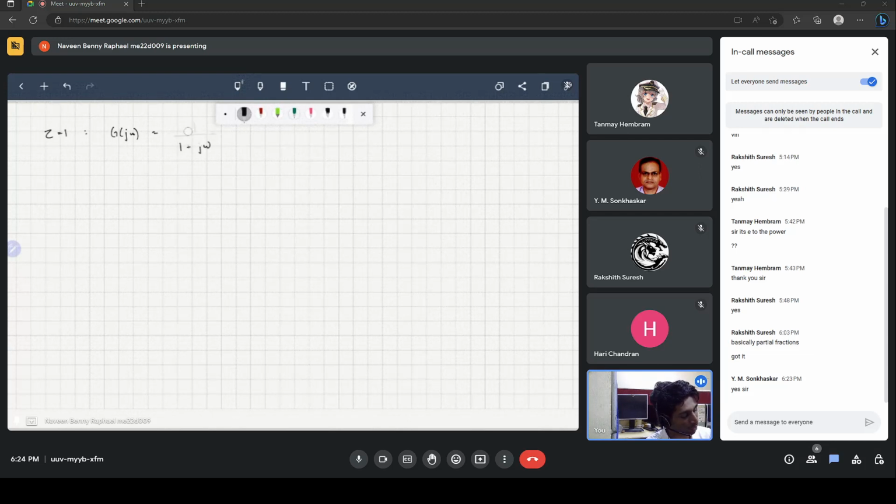Okay, instead of this transfer function, let's consider a transfer function G2(s) equal to 1 plus tau s, and setting tau equal to 1, we see G2(j omega) gives us 1 plus j omega. Now if omega is really small, then this term is dominated by 1, and therefore the argument of this term is very close to 0.